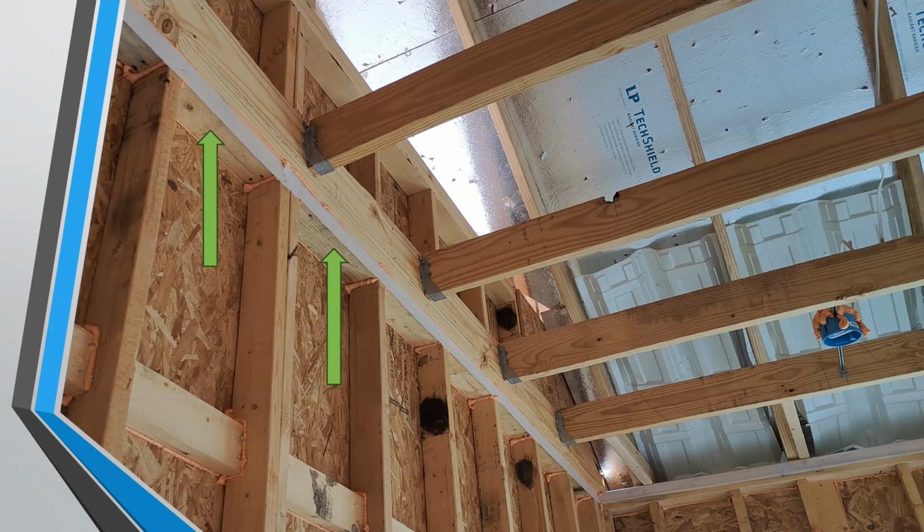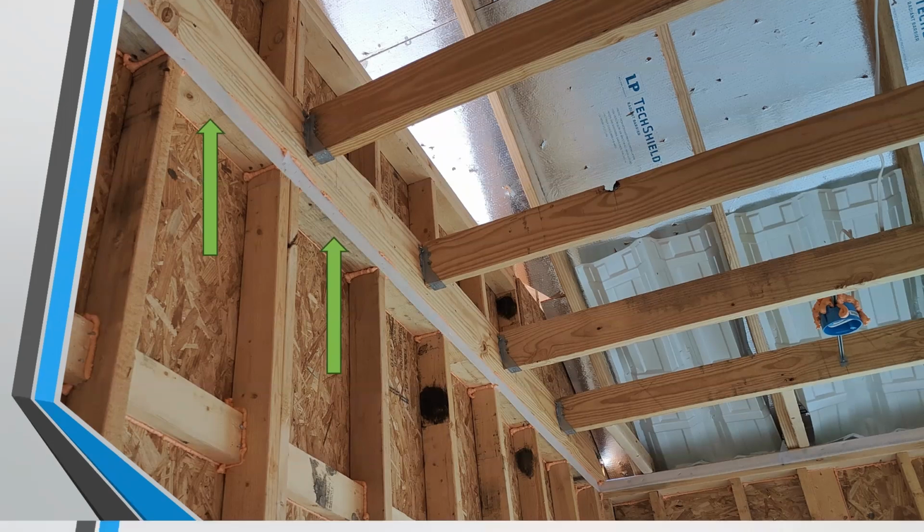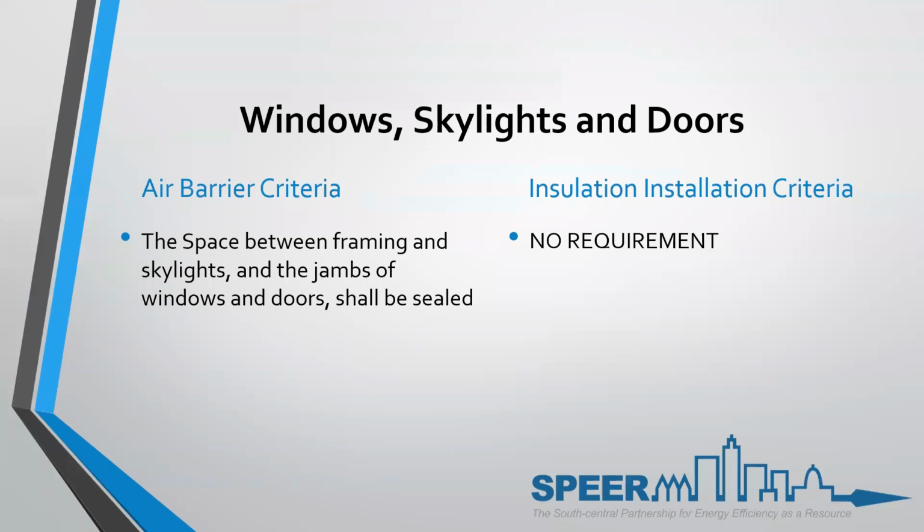But if you've already been doing this because you've already built to 3 air changes per hour, these kind of things shouldn't just be forgotten about. It should always include a complete air tightness. Just because your ACH has gone up doesn't mean the table that we're looking at is to be interpreted as having less meaning. In other words, it needs to be continuous and aligned, with the thermal and air barrier creating the envelope. So always doing it and building it the same way.